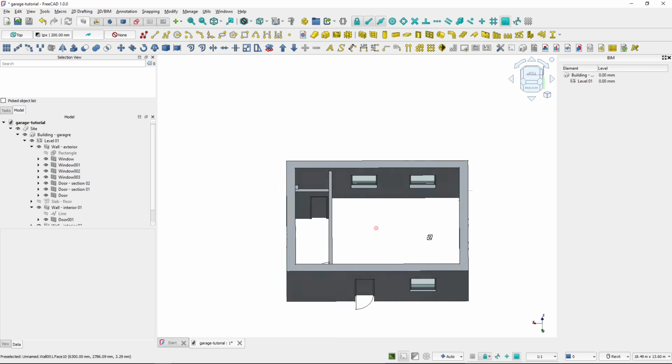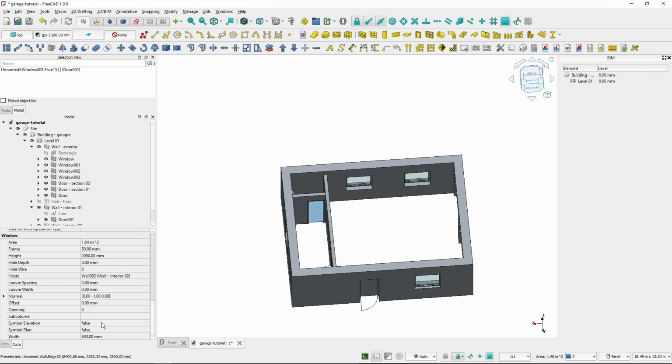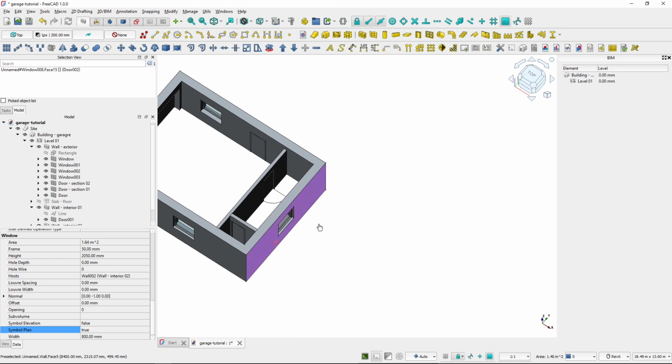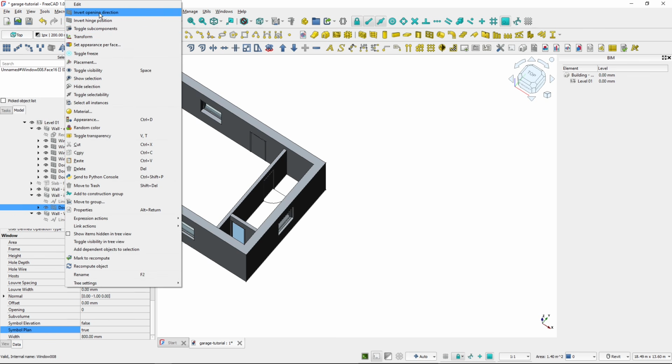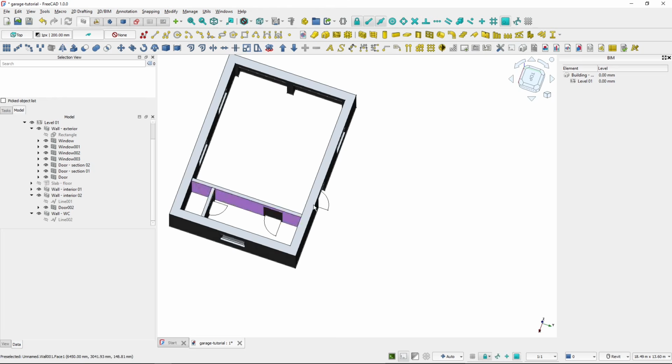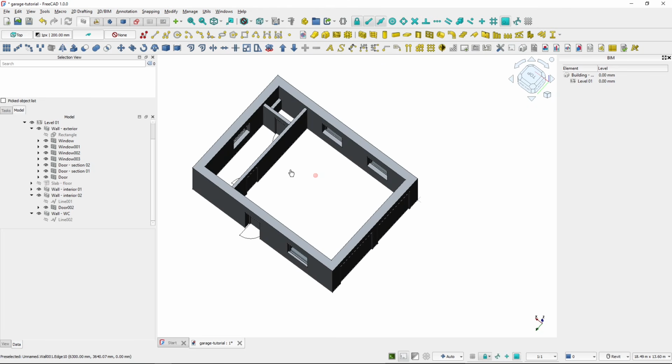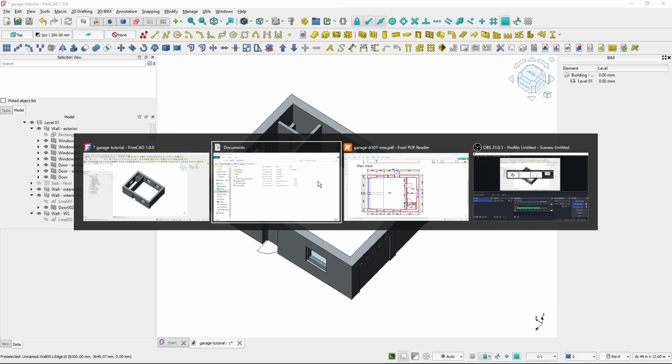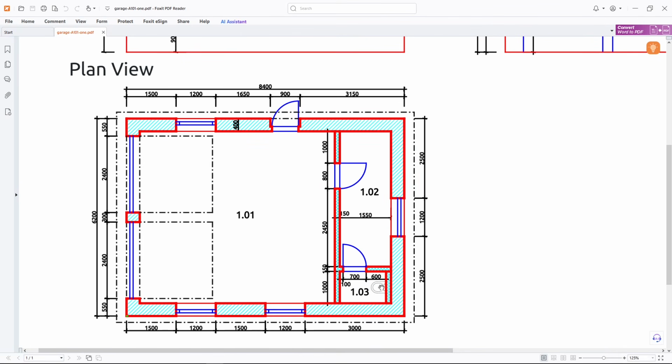Okay. Oh, and I almost forgot again, let's check the opening direction, which is not correct again. So we have to select the door, and it's actually in this wall. So I will right click, invert the opening direction, and also invert the hinge position, so it's opening in the correct direction. So it's moving on nicely, and now let's place the toilet object.